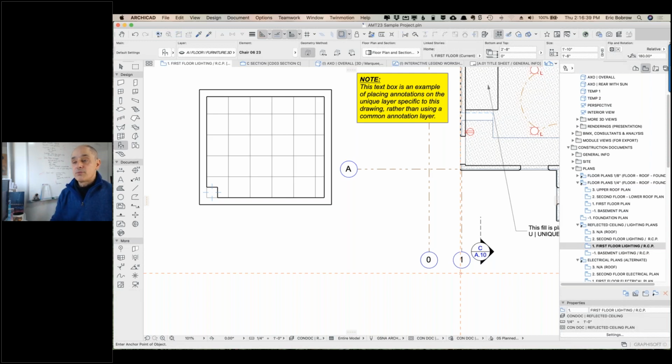But you might want to put some things like your stamp. So you have an official stamp that says, I approve this drawing, or I'm putting my name, my professional reputation behind this drawing that's being issued. Well, you don't want to put that on when you're in preliminary. You want to only put it on when you're submitting. So that would go on a layer that goes off or on. But the rest of the drawings and annotation maybe does go on the ARCHICAD layer.